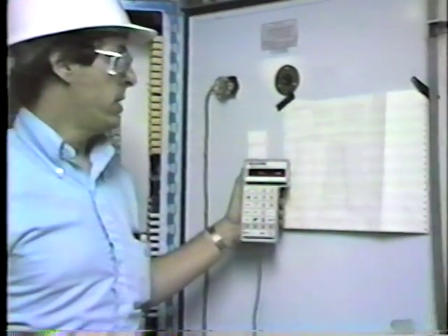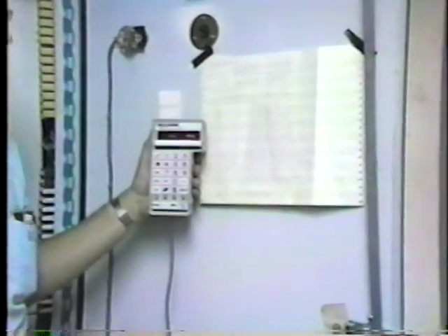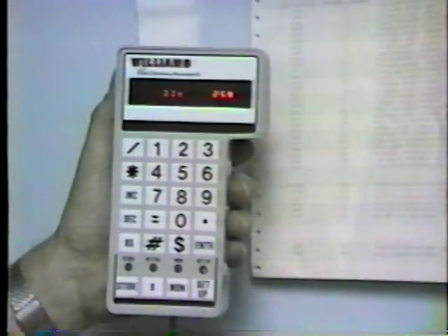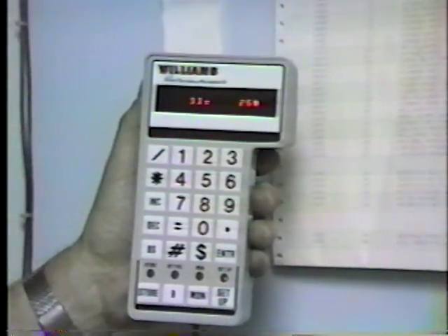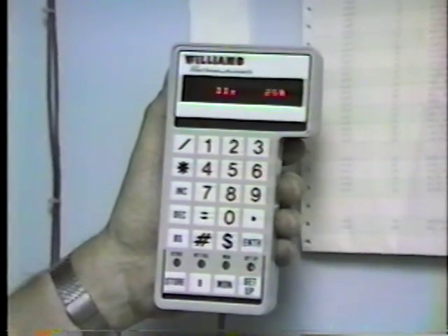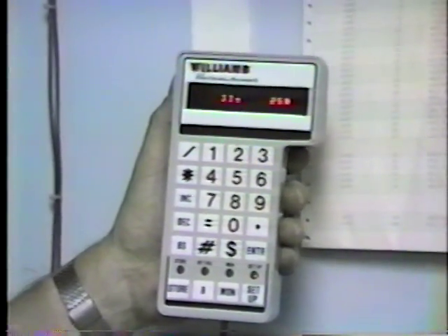Number 11, and now we're into the complement pair, Bob, of the above parameters. In other words, we are looking at the opposite of number 3. That's correct. 3 is the spinner speed at minimum. Now we're going to look at 11, spinner speed at maximum mill. All right, what is that set at? That's 25%. Okay, now you notice before, number 3, minimum was set for 30, and maximum is set for 25.